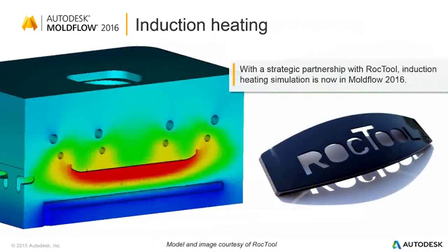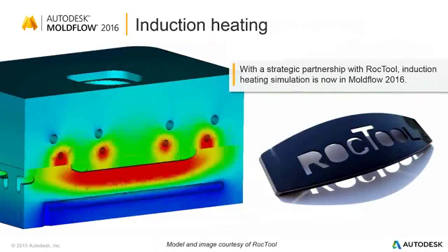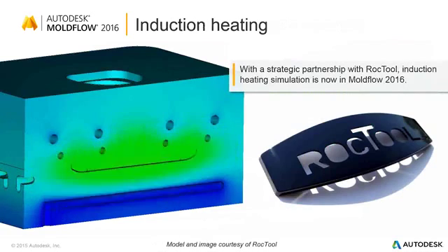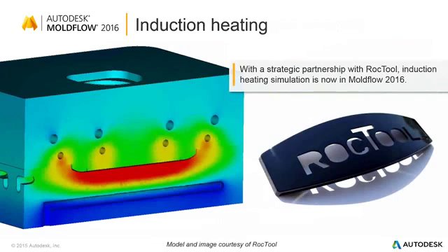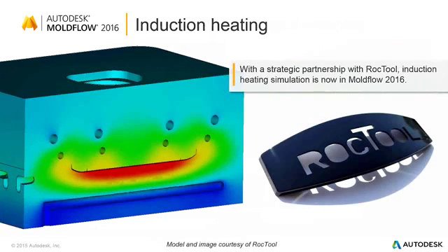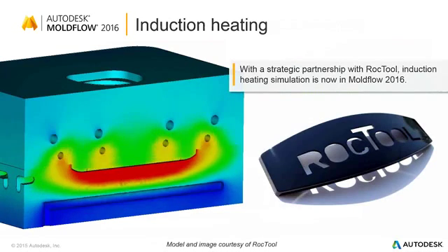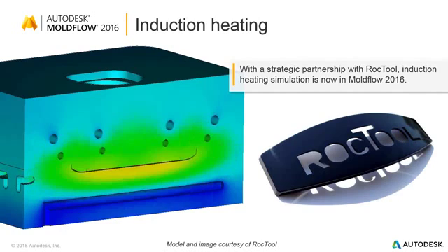Induction heating is a technology that has been starting to make inroads, I think, also in the United States. It's a technology where you build induction coils inside the mold. For those of you who are familiar with induction cooking stoves, you will know that heating up your tea kettle to a boil on an induction stove is incredibly quick.